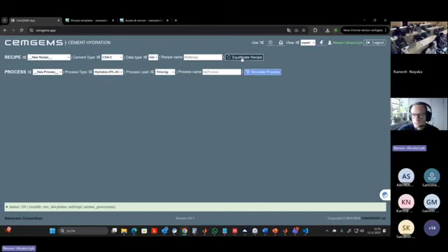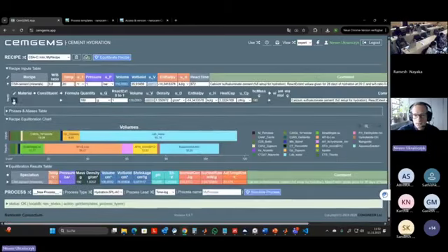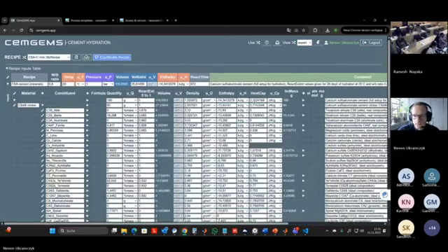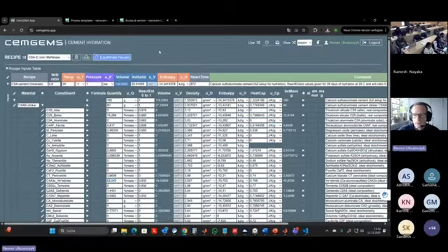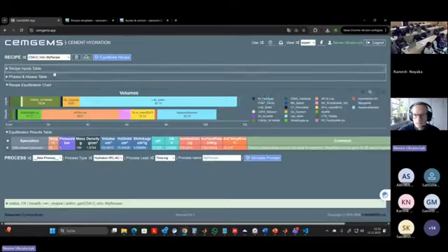Calcium sulfoaluminate cements. So we have the ye'elimite, belite, 20% belite. And this is ye'elimite, 60% ye'elimite. It's the calcium aluminosulfate clinker. And if we equilibrate, we get gypsum and monosulfate mostly. Let's see. Yes, it's the gypsum, stratlingite because we have also silicates, and monosulfate. What is this? Aluminium hydroxide. Okay.